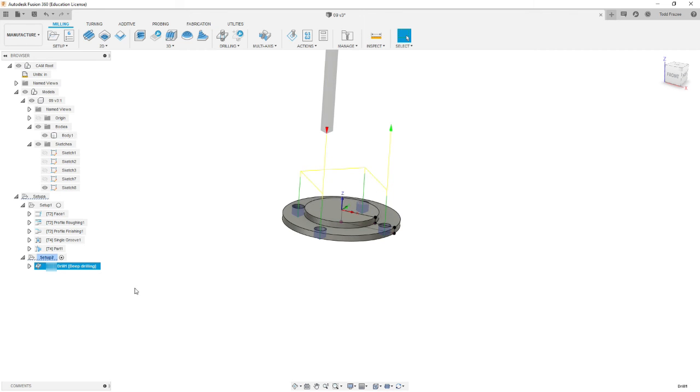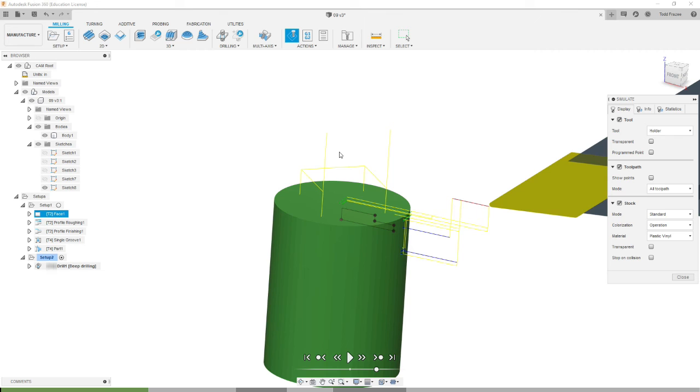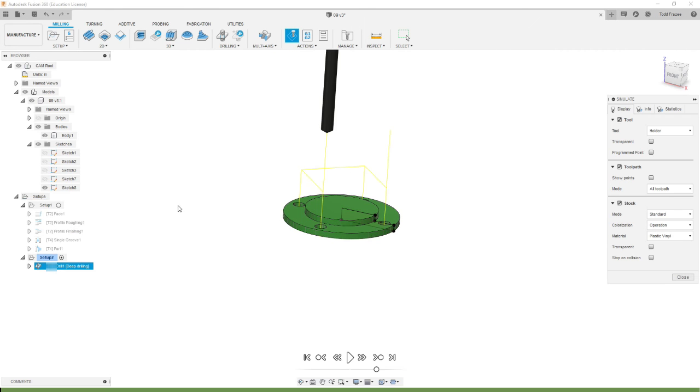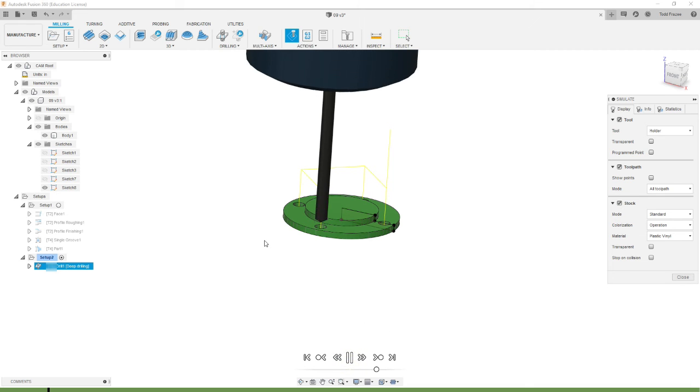Now it'll be important to keep this because you want to program the -10 part, which has the same hole pattern, and we can literally just copy this tool file to the other file when you get to programming the other part. Okay, we're done, and we'll simulate this, and should be pretty straightforward. Wrong stock though. Let's make sure you get the right thing highlighted. There we go. And then make sure your stock's selected, and we have our drilling.